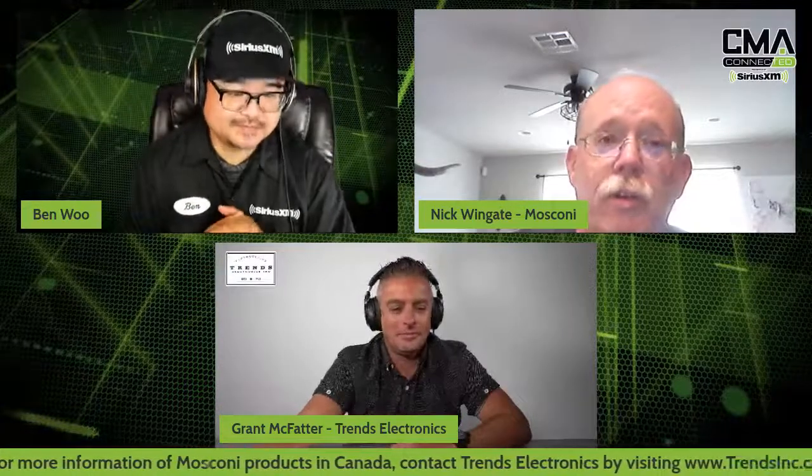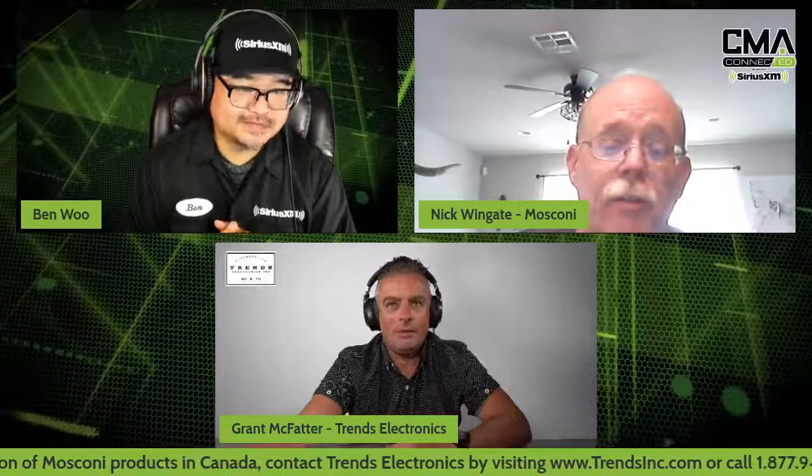Gain set first. Do the -5 and the -10 on the sub, and you'll be fine with your gain overlaps. And put a high pass filter on the tweeter before you get started. Protect the tweeter. Play everything full range. And then play them full range, and you're going to find out what's going to play what real quick.